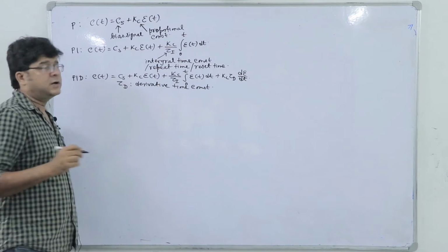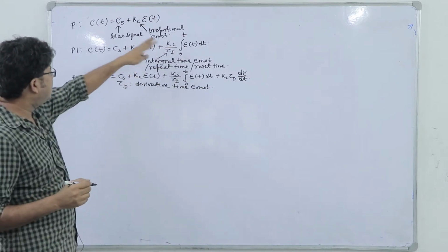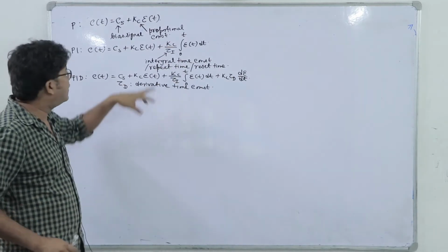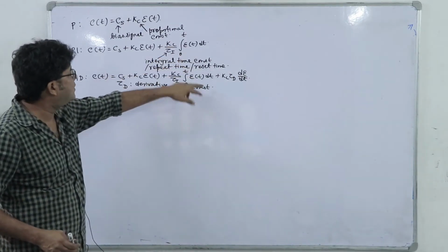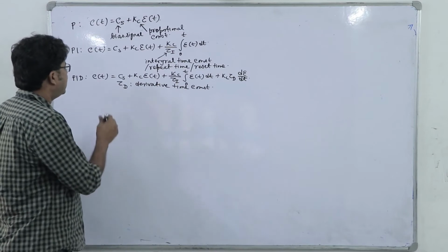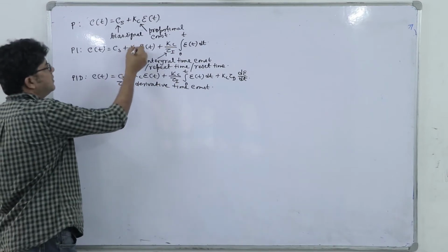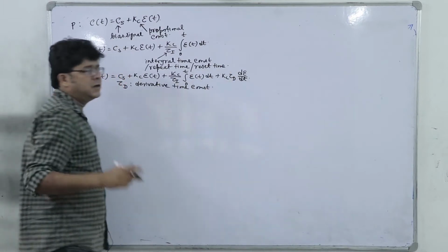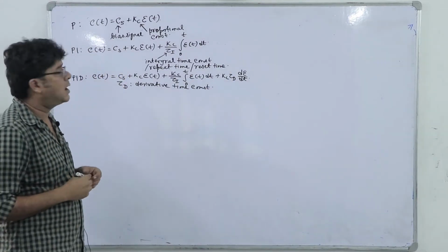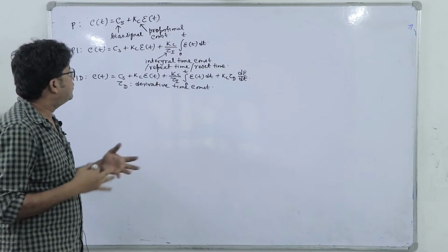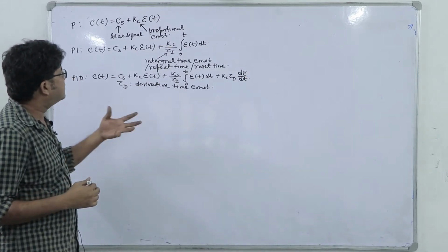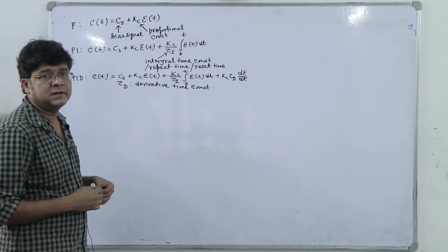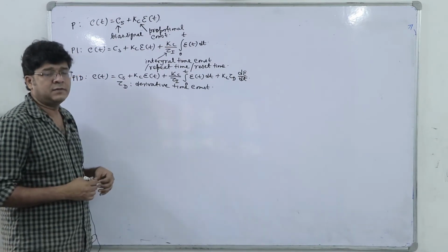So, you have to note that we can individually tune the weightage of the proportional term, the integral term and the derivative term, because the constants are Kc, Kc by tau I and Kc into tau d. Upon tuning Kc, tau I and tau d individually, we can adjust the weightage of these different terms, and that we will discuss in a topic called tuning of the controller.